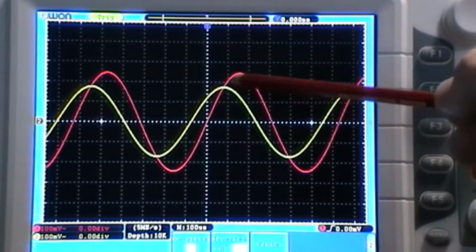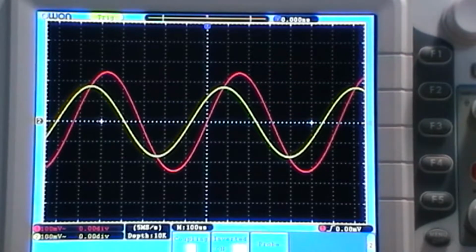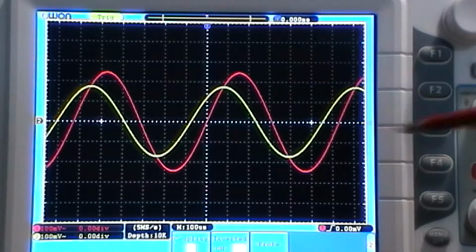It's about minus 3 dB from the original signal, so it always looks around about the same at the cutoff point. If we represent it in this way, you wouldn't know that you've got a different frequency, except for the fact that I've calculated it to be 1.59 kilohertz rather than 723 with the 220 nanofarad, or 159 Hertz with the 1 microfarad capacitor.